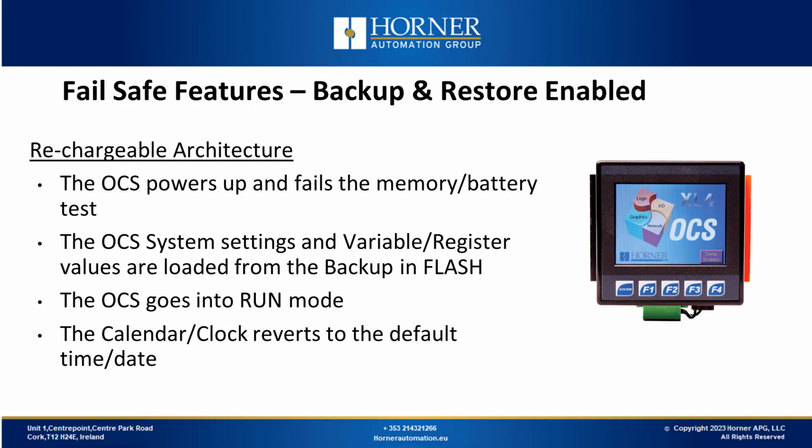If you don't use these features with a traditional architecture, the primary consequence is that you'll lose your program or your variables will reset to zero. You'll encounter the issue of no user screen display and likely receive a phone call from support. In a rechargeable architecture, the main difference is that the system will revert to older registers and you'll lose your calendar clock. However, your program will remain intact.